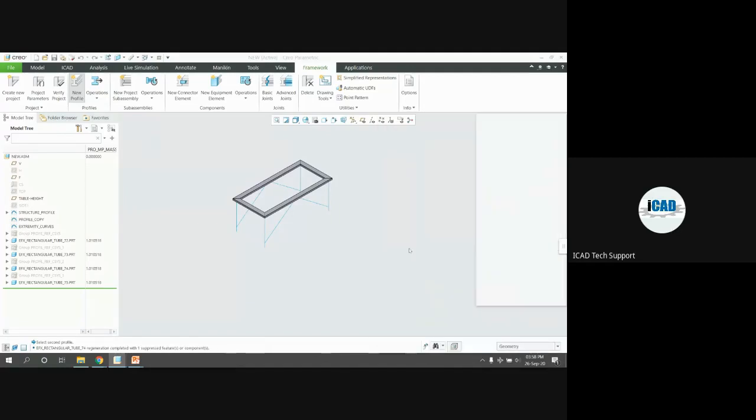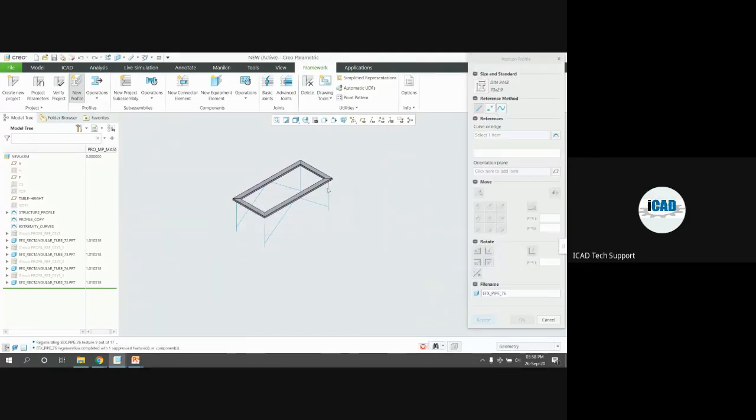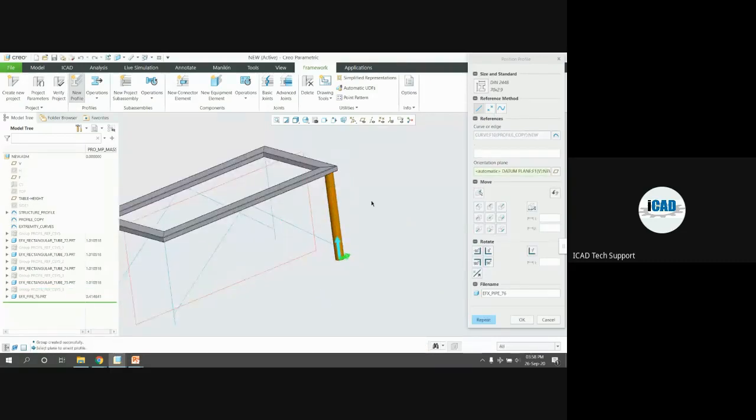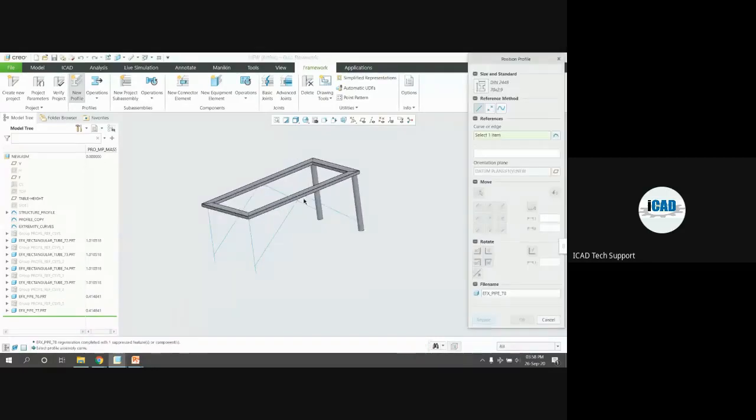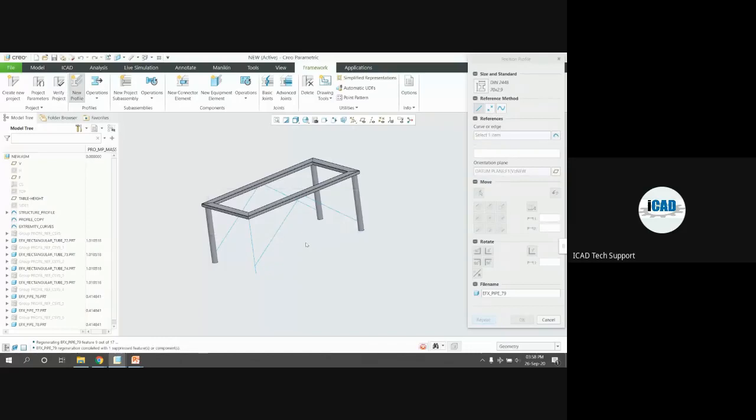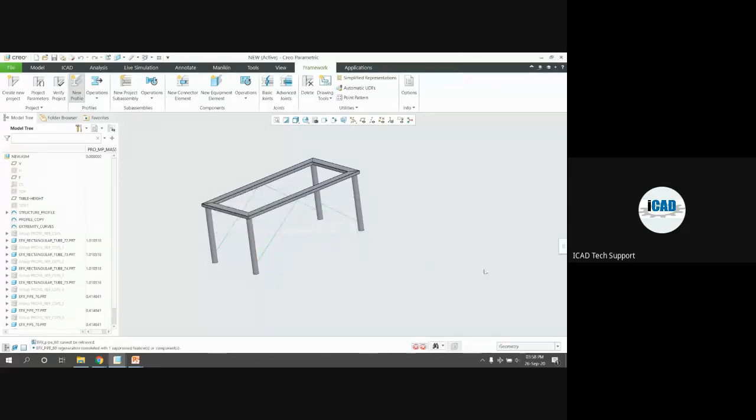Multiple sizes are available for the standard. Click on next. Click on only sketches. You can see the assembly gets installed. Just click the middle click and you can create this assembly very fast. Select the sketch, click on the middle button.